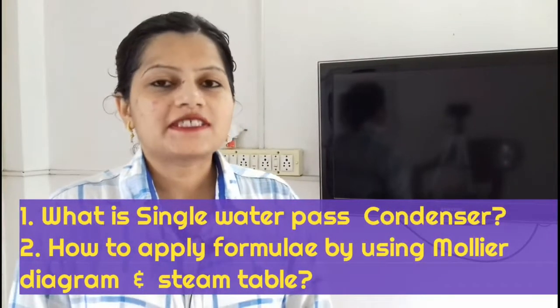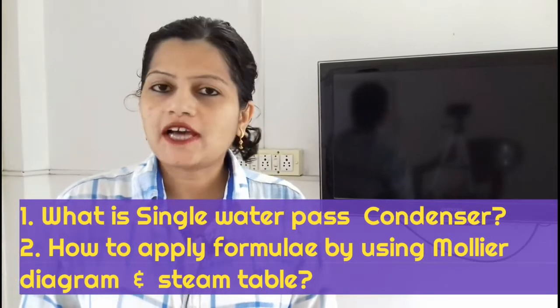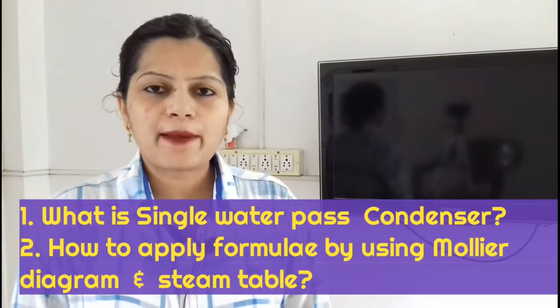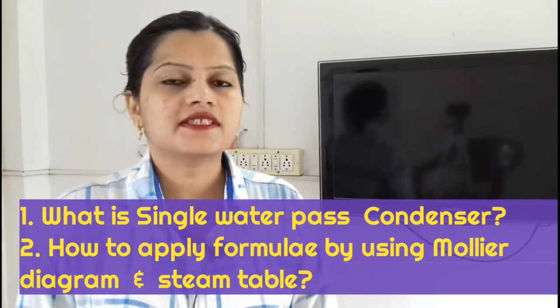Hello ma'am, what is a single water pass condenser? Which formulas are used to solve the problems on single water pass condenser, and how to apply these formulas by using the Mollier diagram as well as the steam table?